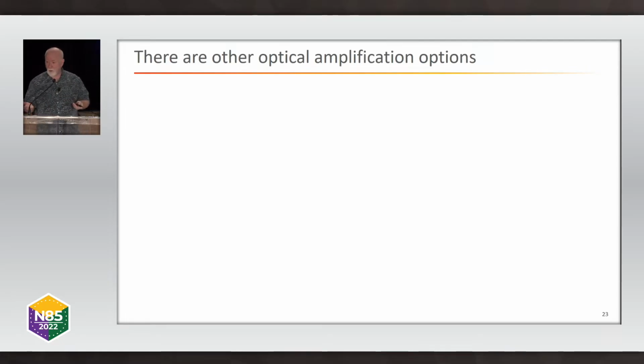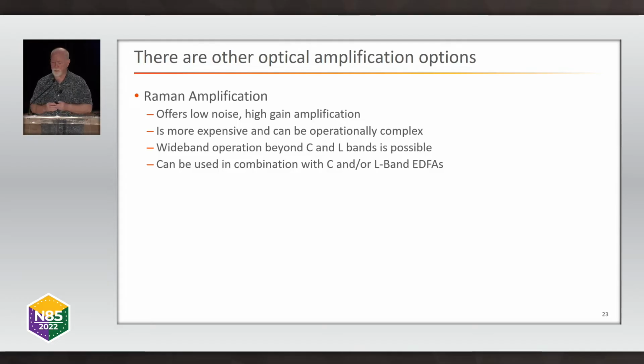And there are other optical amplification options like Raman amplification. And this offers very low noise, high gain amplification. It's more expensive. Some operators don't like to use it because there are operational procedures that you need to train your staff in for Raman.